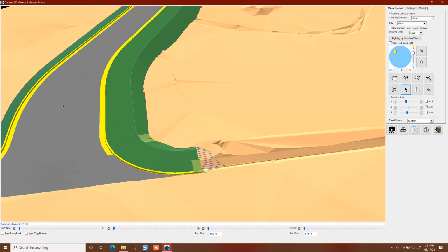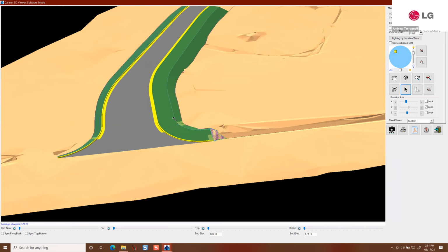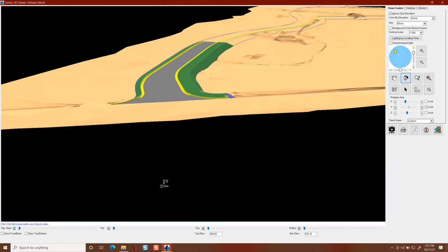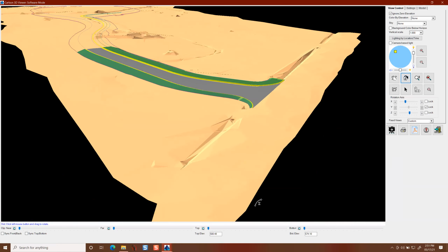Whereas if we had this straight to the center line, and this was another road out here too, then that road tries to catch existing grade, which it would do out there. We would merge edges of pavement and we'd get pushed back here, and then it would fill that in. And I also noticed this. Same thing happened on the other side, but I didn't put that other little piece on it here.